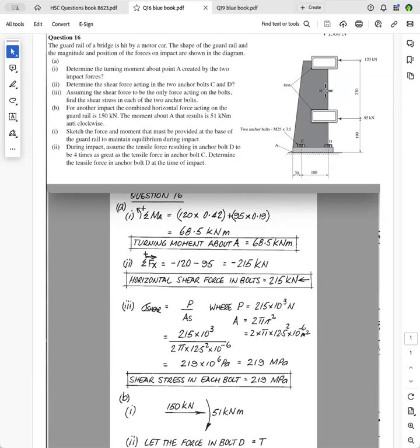If you start to weld carbon steel that's got greater than 0.3% carbon, you have to prepare it by preheating it. Otherwise, with its high thermal gradient, as the weld cools it could embrittle the weld, forming martensite because of the high carbon content. These are the sorts of things that I want you to learn. And if you have any problems, don't hesitate to email me or phone me, and I can explain it to you.